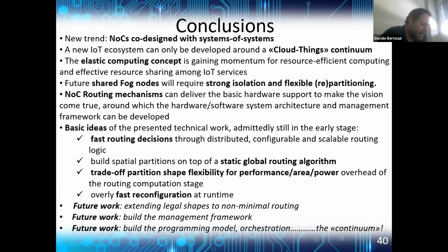Moreover, it's true that in an FPGA you have partial reconfiguration, but in general, it's more tricky to reconfigure things while letting the things going. So in an FPGA, the most straightforward approach is to have static reconfiguration. You stop everything, you reconfigure, and then resume everything.